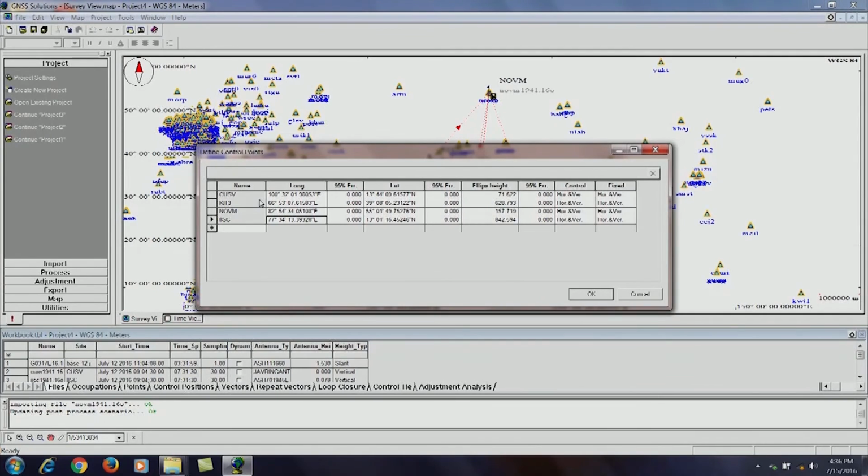Now for CUSV we have the actual longitude, then latitude 13.7359, then ellipsoidal height 76.06. For KIT3 it is 66.88, latitude 39.14 and height 643.